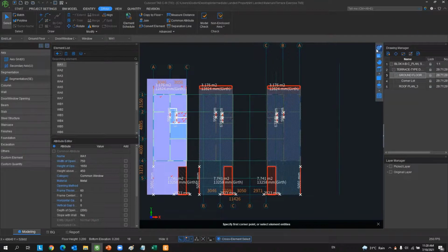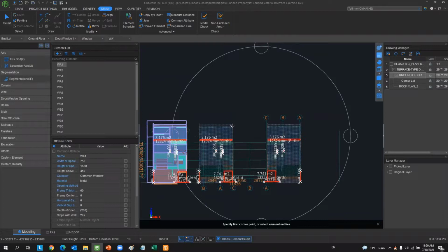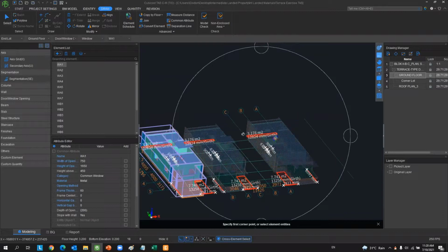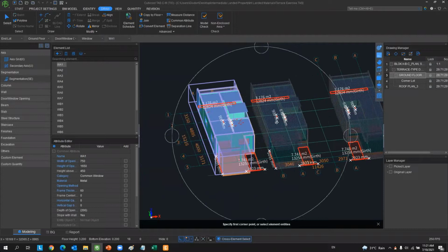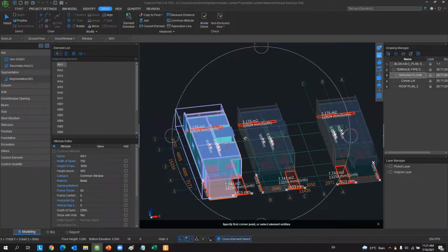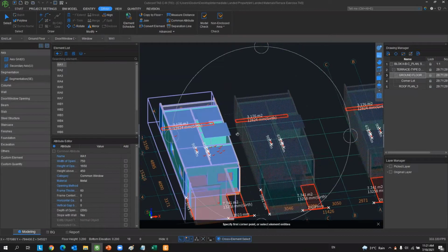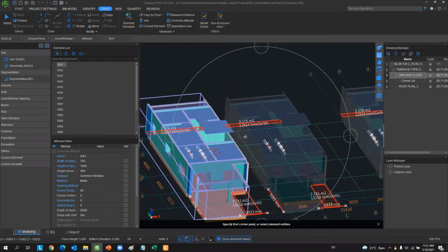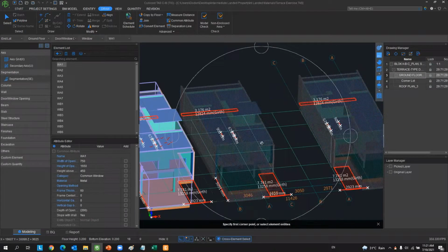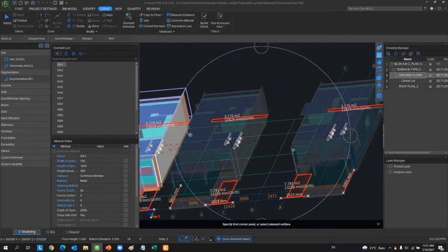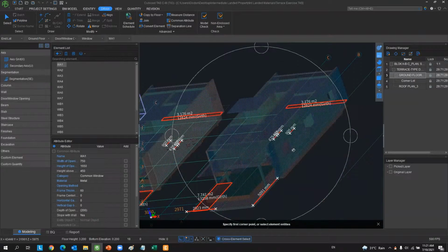Remember everyone, once you do the modeling, you need to make sure the buildings are logical. Say you're doing terrace houses, it is impossible that you will have a shed wall with a window opening. Those are the modifications that we're going to perform. We need to check the logicality. And for this part, you will also need to add external finishes.